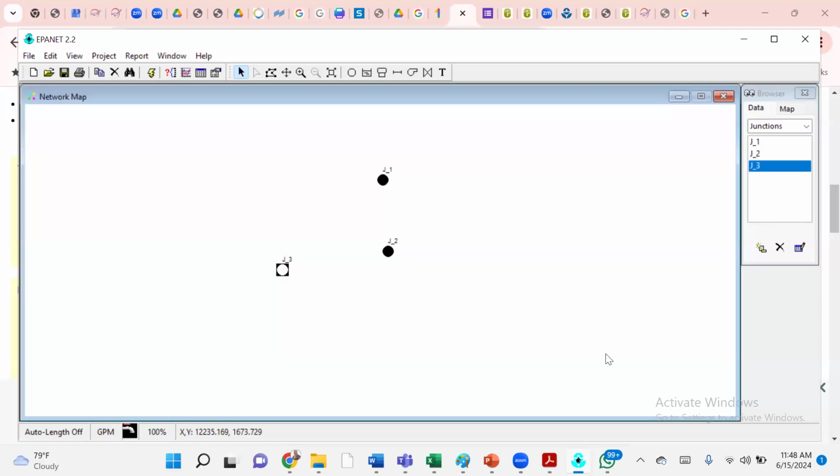So have you seen that the thing has increased? And it has also introduced J1 and J2 for me. I will now go here and click pipe. I will click on the center. Once you click on the center, it will turn to a pencil. You know that you've gotten it. If I click on the center, I'll remove my hand from the mouse. See, I can move around. Please don't click again until I go to the next center. And I click again. And once I click, the nodes will disappear to a cross, telling me that I've established a section. And it will give me P1.